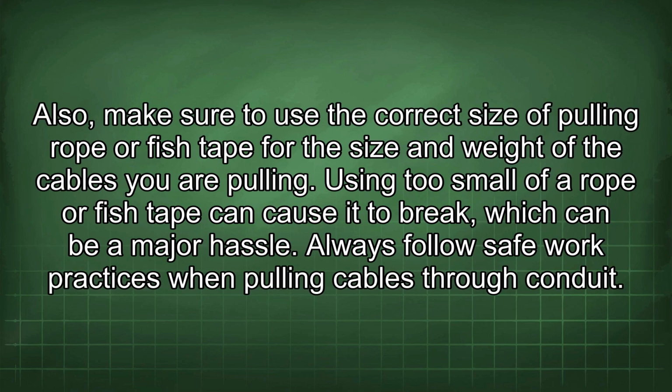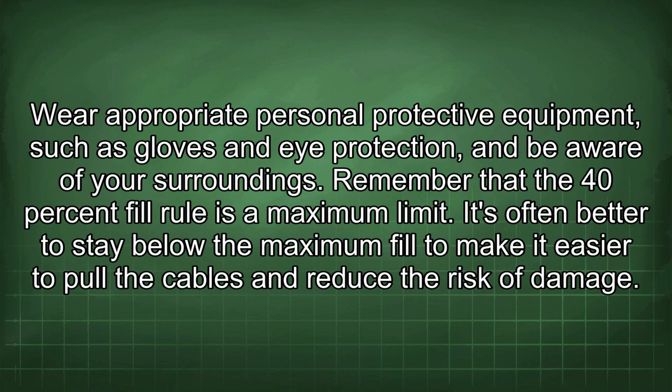Also, make sure to use the correct size of pulling rope or fish tape for the size and weight of the cables you are pulling. Using too small of a rope or fish tape can cause it to break, which can be a major hassle. Always follow safe work practices when pulling cables through conduit. Wear appropriate personal protective equipment such as gloves and eye protection, and be aware of your surroundings.